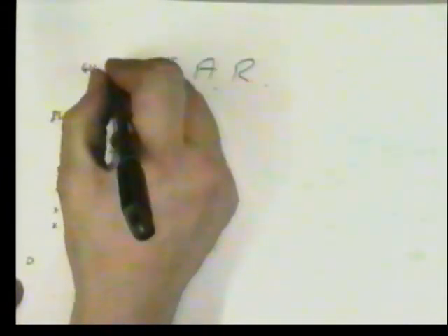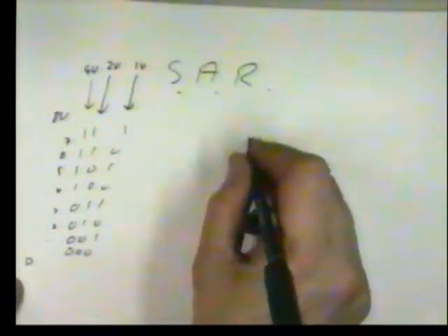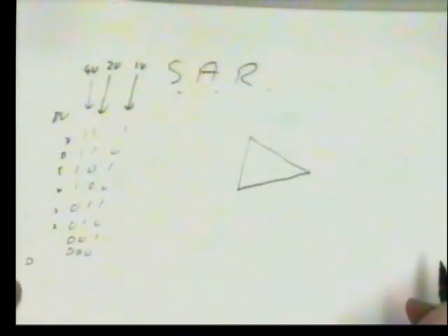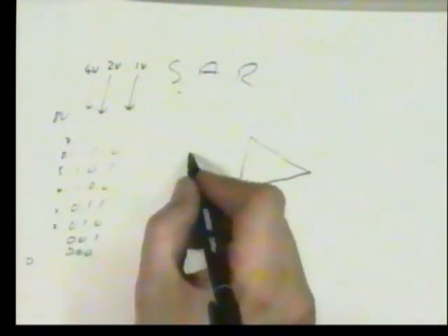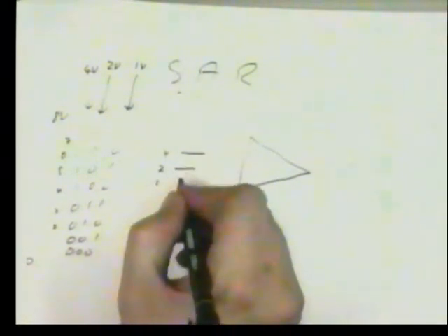The next bit means 2 volts. The next bit means 1 volt. They're halving each time. Pure binary progression. So the way that we use an SAR is that we try out each of our voltages in turn, from the most significant down to the least significant. So firstly, here's our 4 volt, our 2 volt and our 1 volt.